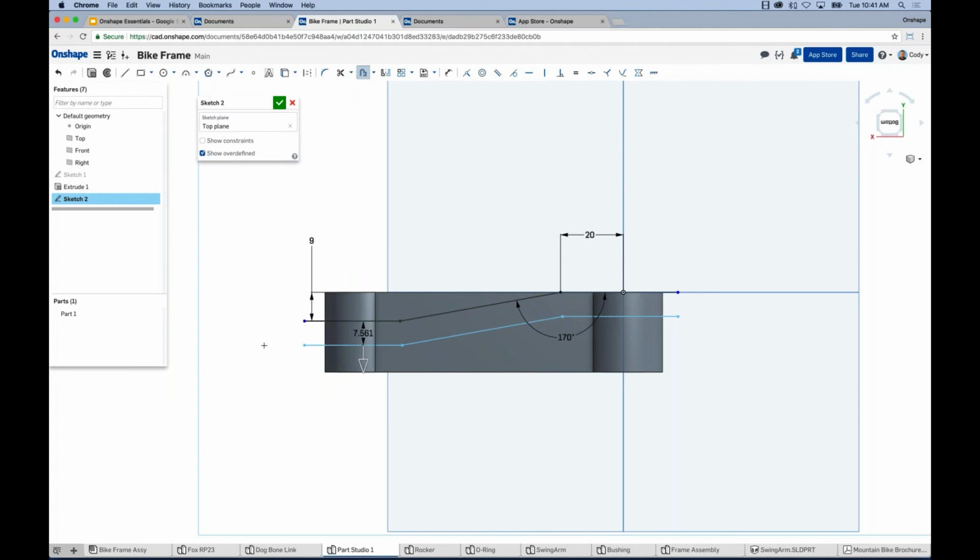Just left-click drag. So I left-click, we'll enter the offset value. In this case, we want an 8mm offset, and there we are. We have the offset 3 lines. The last thing we're going to do is close these things up and attach them to the ends of the part.